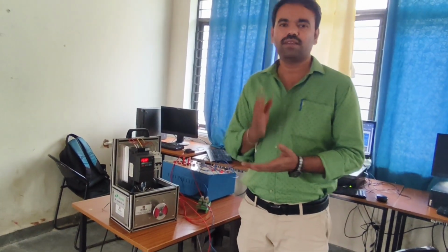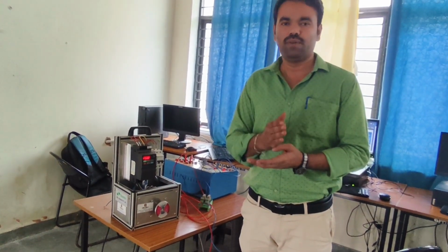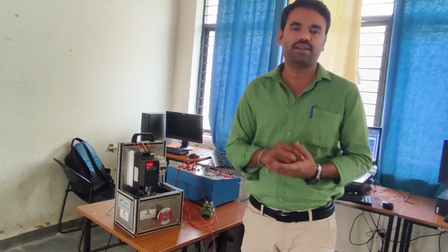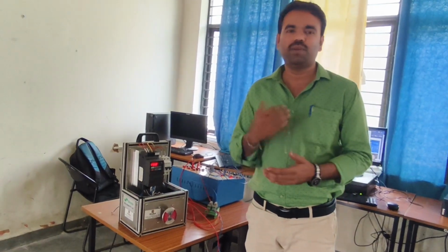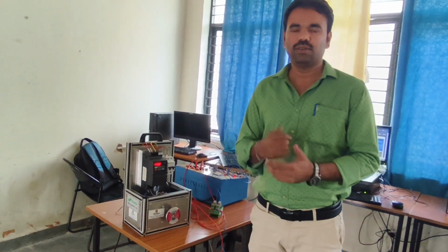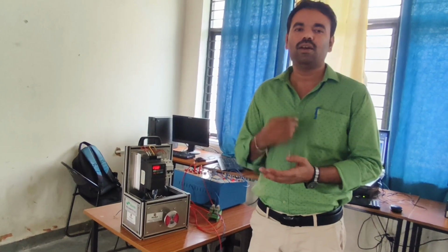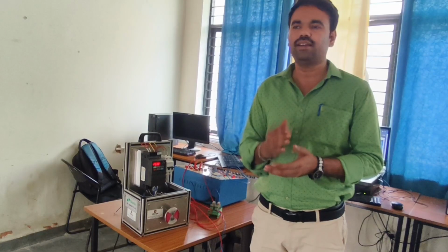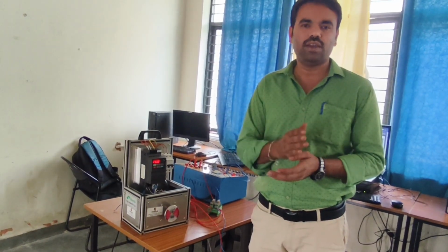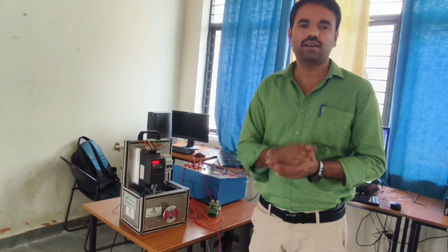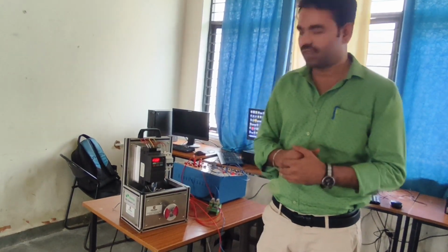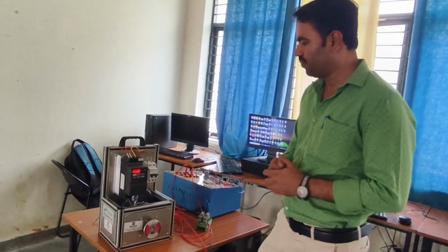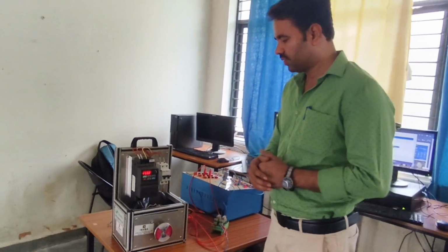In such a case, the conveyor belt has to be moved at two different speeds. One speed for sachet and another speed for container. We assume that the container may be half liter or 1 liter. So filling the containers will take more time compared to the sachet. In such cases, the conveyor has to move slowly for containers compared to the sachet. So for that application, we are implementing the speed control of induction motor using VFD.